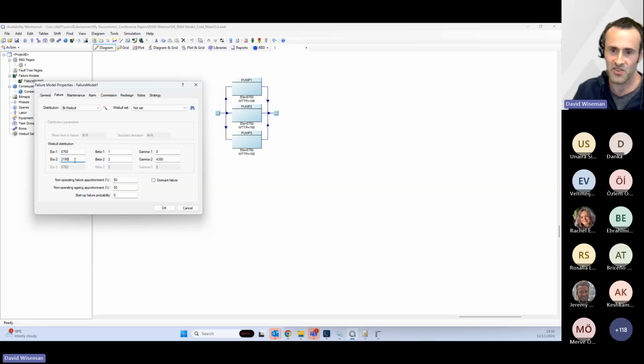But I have a second distribution dropped on top of that. This one has a shorter lifetime, about 3 months. So this failure happens more often. And most importantly, it has a shape parameter of 2. Any shape parameter greater than 1 indicates that the failure rate is going up with time, things like wear out or fatigue. Then I've got a location parameter, gamma, that indicates when those failures begin. And that is set to about 6 months.